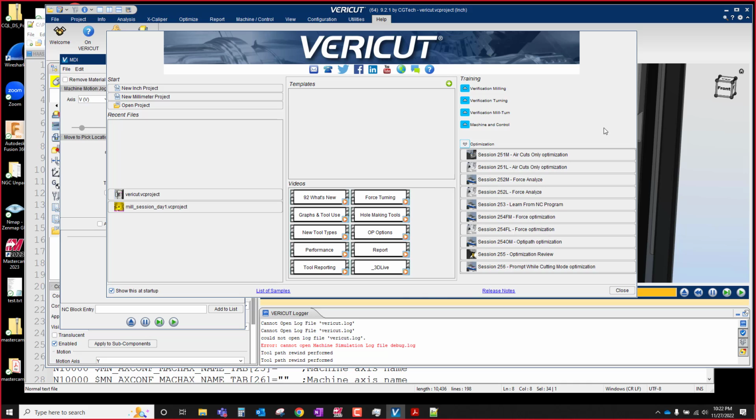But it makes so much difference having that scallop in the center, so you can actually see when you're leaving built-up stuff in the center of the tool. I even said on the forums once that it'd be nice to have a collision or a no-cut zone in there too, so when you exceed it, it doesn't still consider that set screw as just blowing away material. You can eventually do that in Vericut.